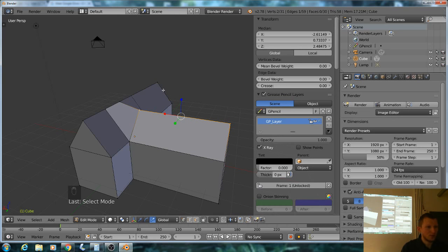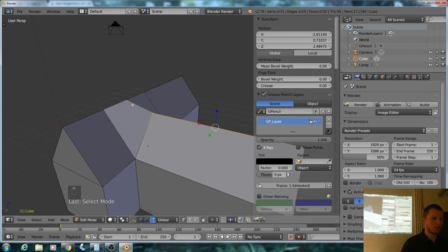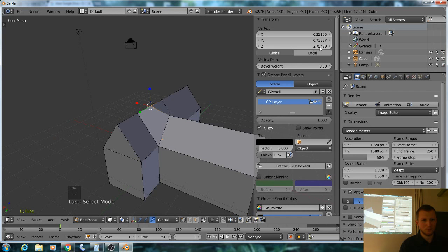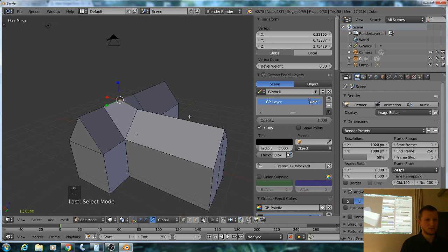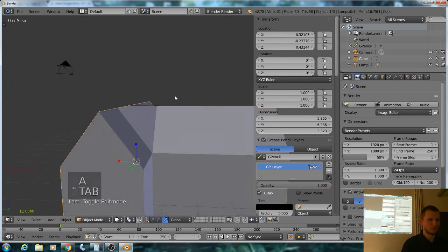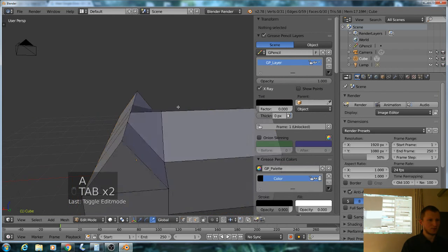So we have to check how high this vertex is. It's some sort of point something numbers. We can copy and paste it. If we click on it, we can press Ctrl+C and Ctrl+V for those. Press enter, and it should be exactly at the same height as that one.